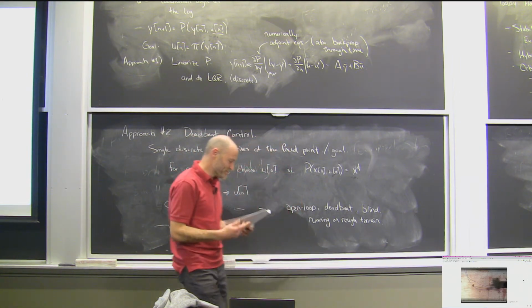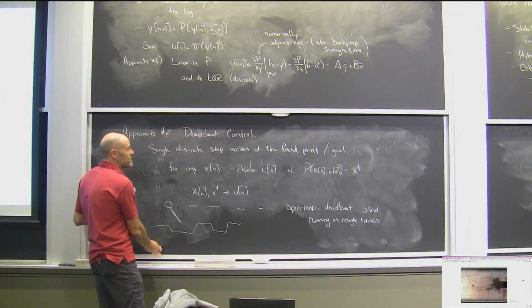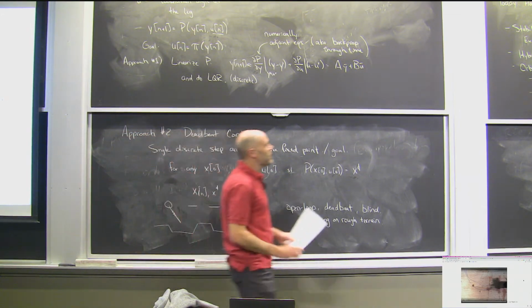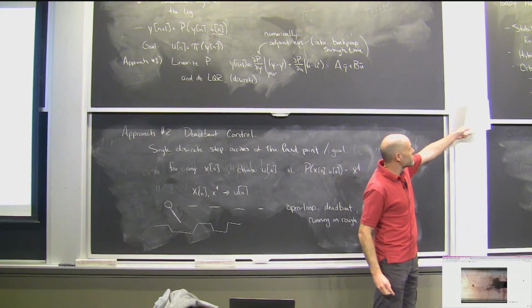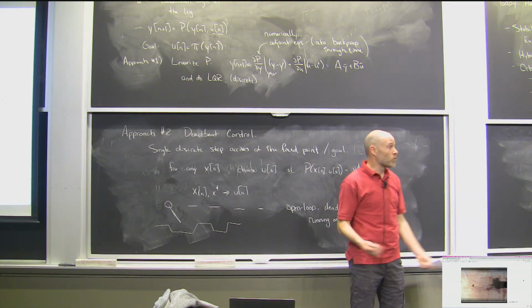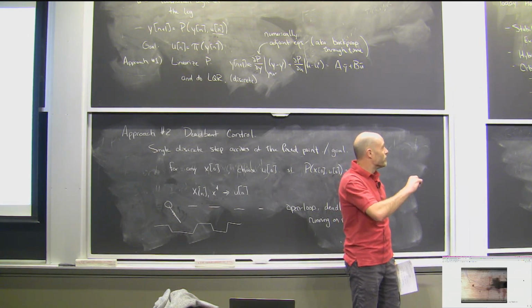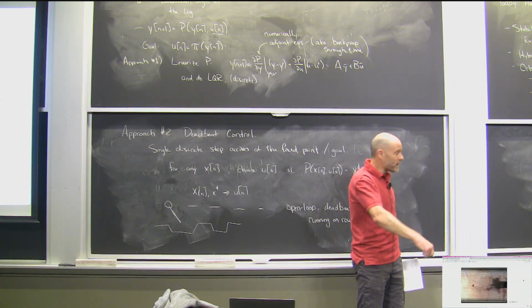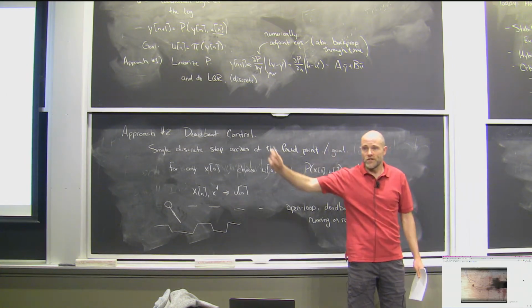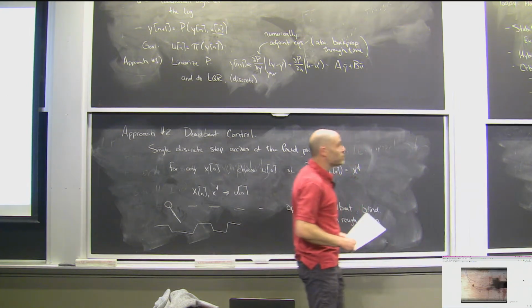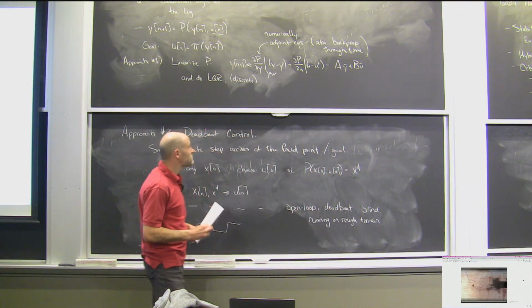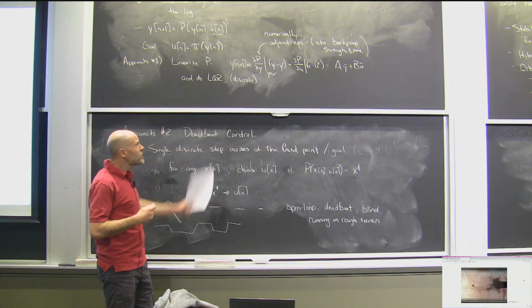Okay, good. So let's generalize this. This was stabilizing the Poincare map, but I want to bring it back to doing continuous control decisions, where you could not just fix one control for the entire cycle, but actually continuously change your torques, let's say, over the duration of a cycle. You would expect that to be a richer class, right? And you could do it in this framework.